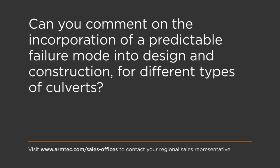The fortunate thing is that flexible culverts are quite resilient, and if you can see the culvert, they do not often result in catastrophic failure. You'll often see warning signs like sagging or cracking pavement before you actually reach failure. You'll usually get deflection before failure. So as with any type of flexible system, you get warning signs.